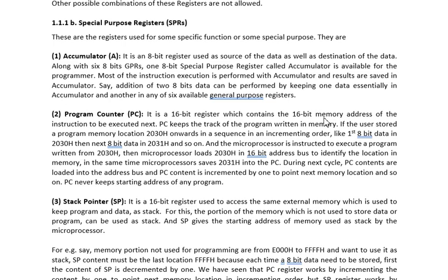In binary, 0000 can be written as 0H, and another 4 zeros 0000 can be another 0H, so it can be 00H. So 8 zeros in binary can be written as 00H, or 01H, which is in binary 00000001. Then 02H, 03H. This way you can represent 8-bit data in hexadecimal.